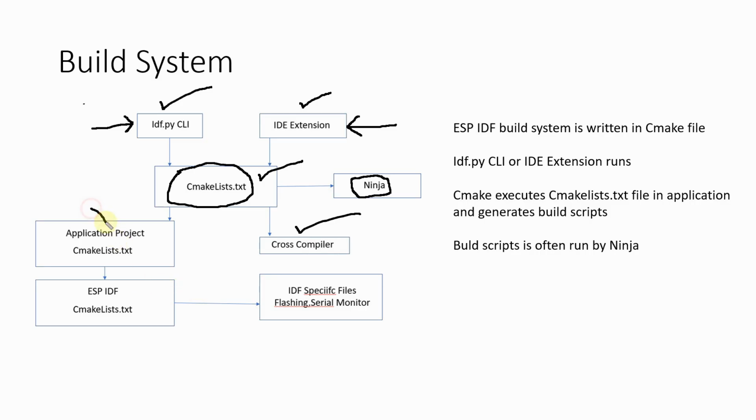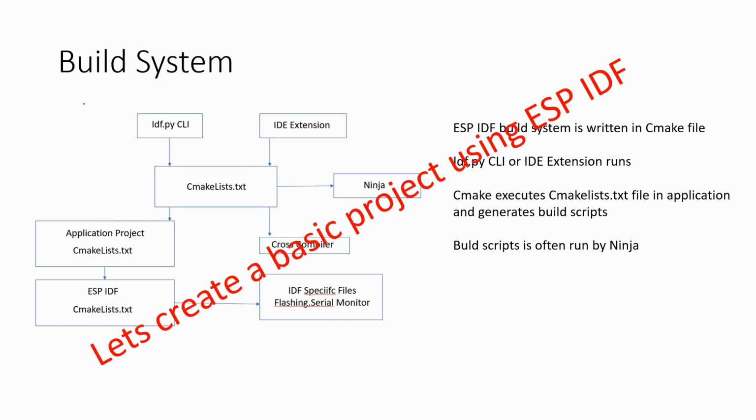and there are various other CMakeLists files also available for an application. ESP-IDF CMakeLists file for all the primary ESP-IDF application libraries, and further that file will be converted into bin for flashing onto the ESP32 SoC. So this is the basic process of build system in ESP-IDF.